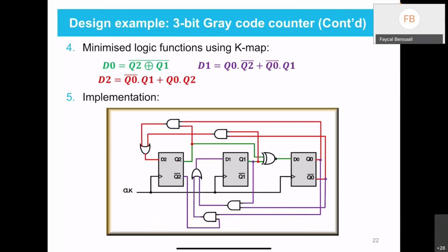Of course, you can use a K-map, but sometimes the K-map doesn't help and doesn't give you the best one. I mean, it cannot be simplified. You can rearrange things to get it into an XOR gate, or so. This is my circuit, with multiple gates, and it gives me the sequence that I want. So it's not a normal counter; it gives a different sequence.